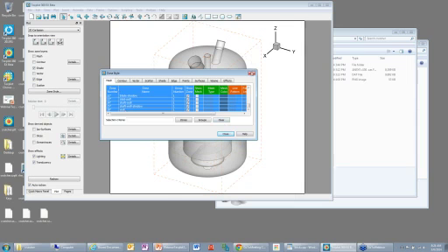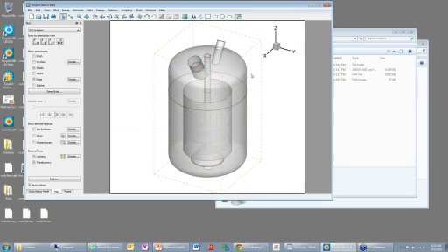Mesh generators commonly will output surfaces as well as the volume mesh if you tell them to, and you want those so that you can see them later without having Tecplot do that boundary extraction, which requires all your data to be loaded. So that was the example of using 360 as your data conversion.